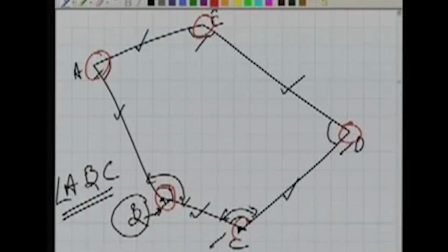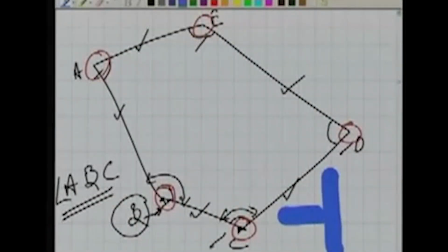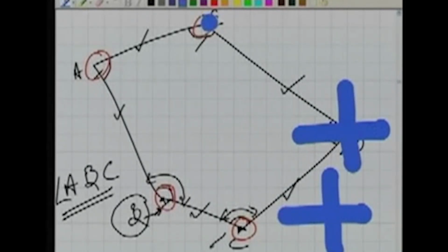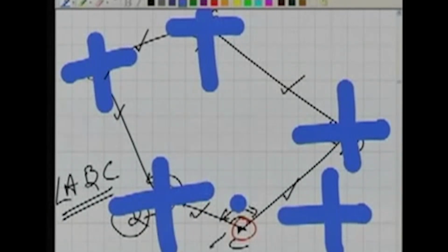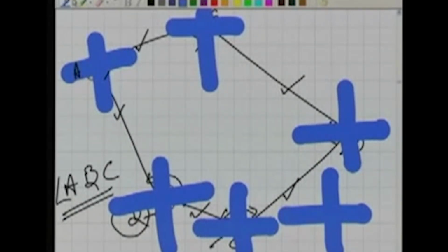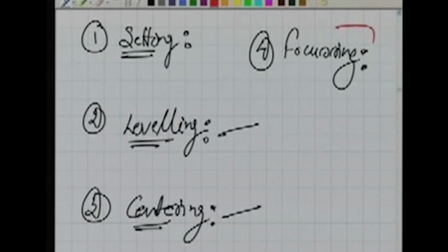All these points, the traverse stations, are marked like that on the ground. Or if you are doing temporary work, you can take some paint and draw some lines on the ground. These are the lines which mark the point. Basically the job now is, when you are occupying here, you want to put your instrument over these points. This is how you can measure these angles, and this is why we need to do all these temporary adjustments.